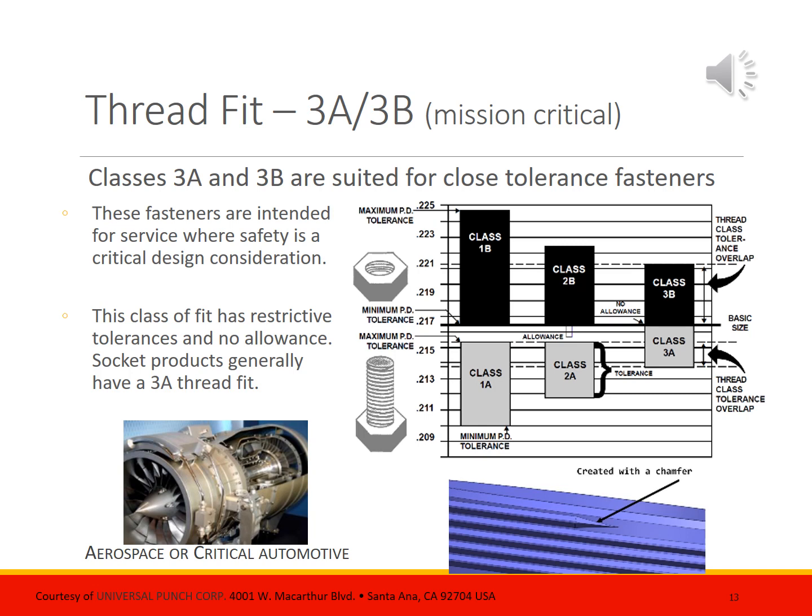Now, because of a tighter fit, thread form and lead-in, the thread geometry is critical. You can see too from the graph, the mating pitch diameters are more closely matched, which provides greater thread overlap and higher strength. With this, however, comes tighter manufacturing tolerances, more inspection, tighter process control, and more headaches for the manufacturing engineer. However, when you have a process that's dialed in, there is certainly a well-earned pride in producing high-quality Class 3A bolts and Class 3B nuts.